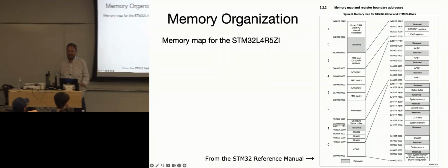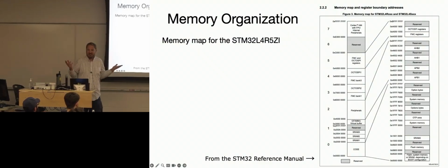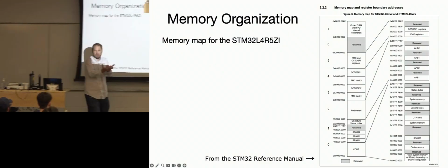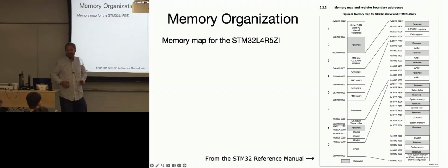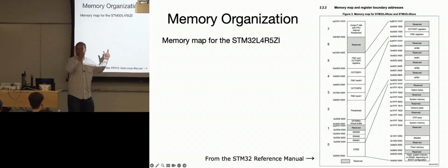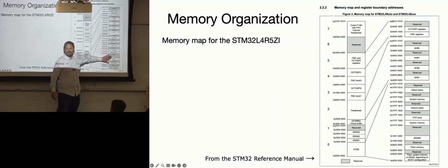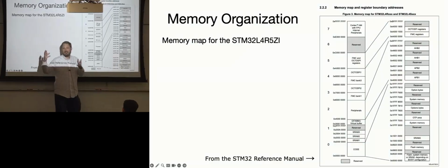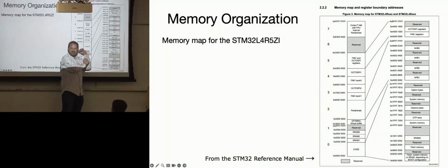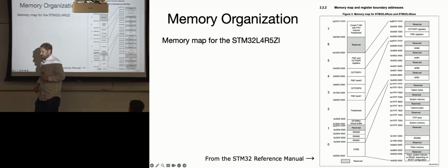Can we use those addresses? Or they don't exist, you just can't write to them? Yeah, there's literally no storage elements there, and your compiler should throw an error, because your compiler should know what chip you're using. So there's just nothing there for you to use. They just didn't implement it. But instead of having ARM keep track of everybody's little implementation and making it as small as possible, they just say, here are the regions you can operate in.